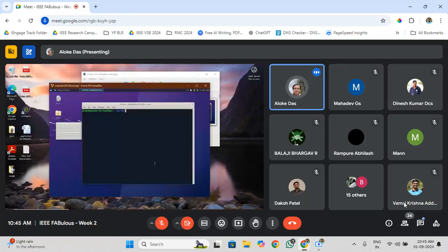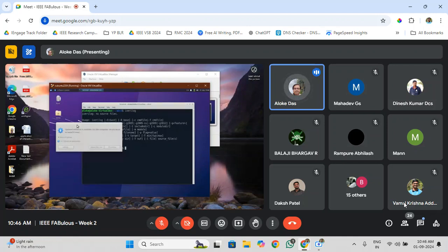Actually, the first thing is iVerilog. This is the Verilog compiler and simulator we have to install. By default it will not be installed. If you click okay, now it has come, let me finish it. By default after logging in, on starting the machine, this may or may not come. If it comes, you click like this, then the window will come, then you click on install now.